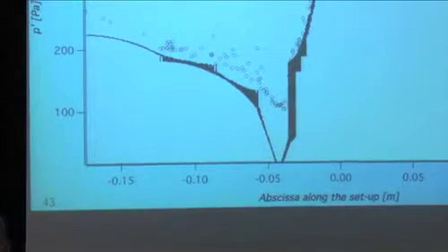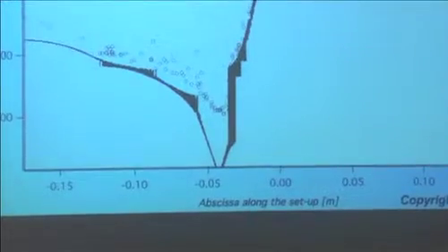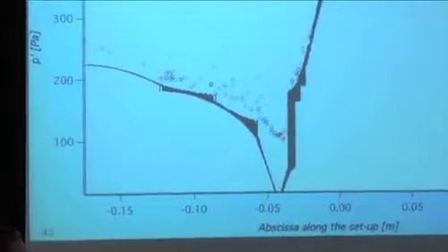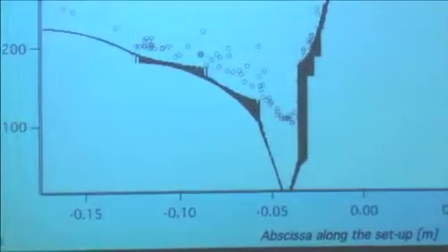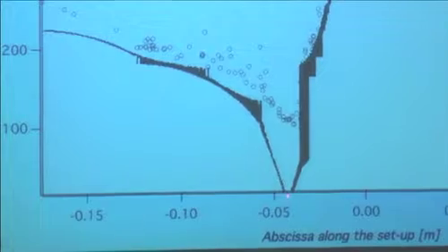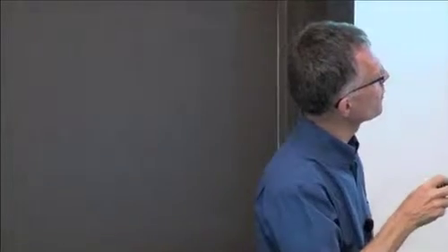By the way, just a small comment here. This zone here is the throat of the burner. And it makes sense at this location that you have more P prime in the LES than in the acoustic solver. Because in the LES, you capture P prime due to everything, that means vortices and acoustic modes, while in the acoustic solver, you capture only the acoustic part. Remember that in the real world, a pressure fluctuation can be due to an acoustic wave or to the center of a vortex, for example. So LES captures both. This is why normally you should always have larger P primes in the LES than in the acoustic solver, especially in the zones where you have a lot of vorticity.